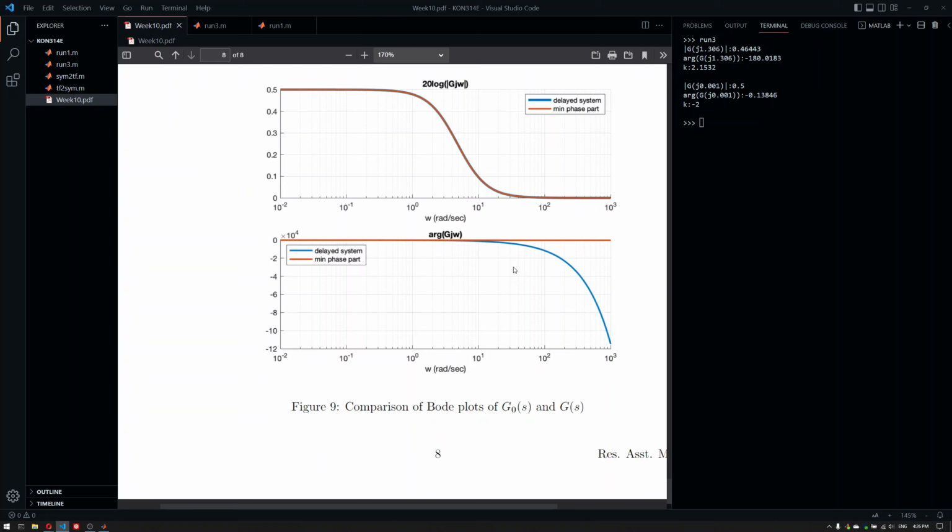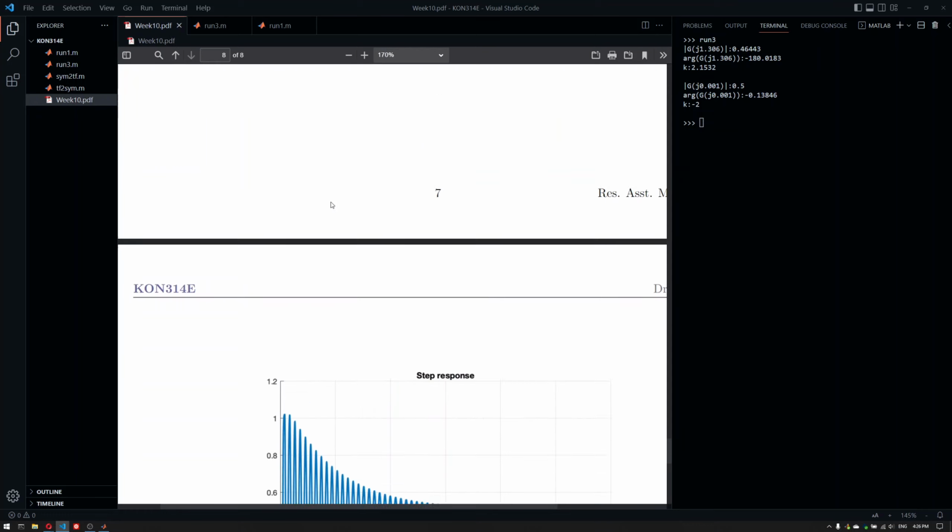So when you add delay to a system, you can also assume that you will hit the stability bound much earlier. Therefore, your stability interval will drop down because you have a certain gain value here. And if you hit it earlier, the stability bound will be a smaller interval. So that's basically it for today.